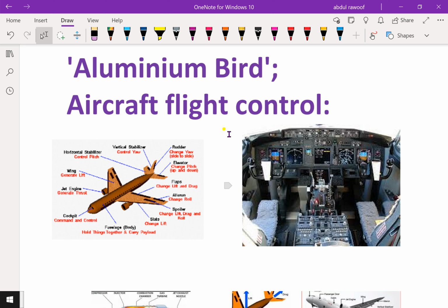The flight control consists of the equipment and methods used to maneuver the drone in flight. Depending on the type of drone, there are different ways of maintaining control. For example, servos attached to sensors can be used to operate the tail control surfaces. In the fixed wing drone, the measurements taken from the various sensors are used as inputs to software PID control loops.